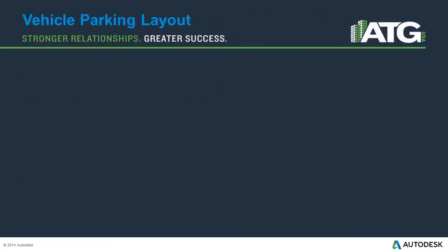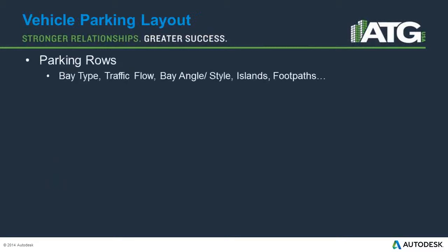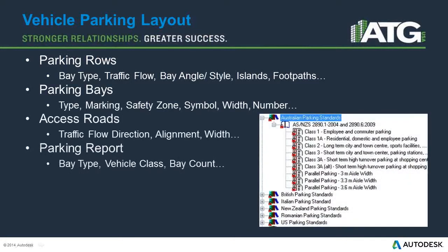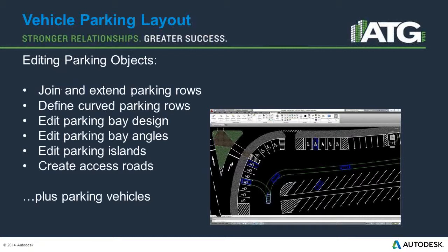A lot of the parking standards have been supplied with Autodesk Vehicle Tracking, and they create a rule-based design engine from which to design your parking lot. They define a large number of features that can be associated within the parking areas. As with vehicles, you can edit and create your own custom parking standards. Once placed in the drawing, the parking rows remain intelligent objects, allowing you to edit them freely using many grips that are available.